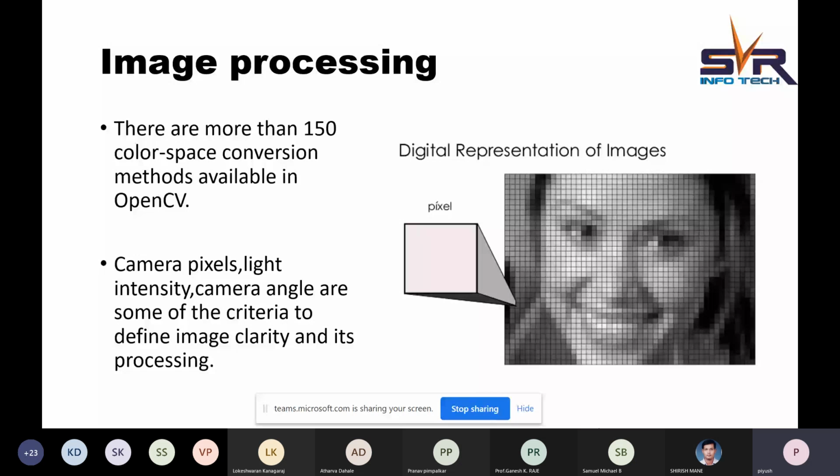Then we have camera angle. Of course, camera angle is important because if the workspace and the camera are not placed parallel, then there will be a difference in each coordinate, which will be quite hard to calibrate with the robotic arm. Suppose you have two planes parallel to each other, then the coordinate distance between them will simply be a multiplication scaling factor, and will be the same.